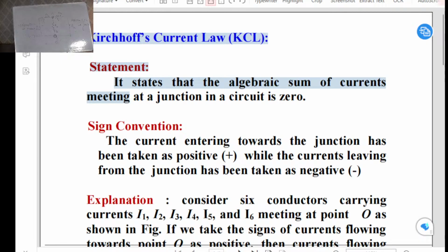If you draw any circuit diagram, this is confirmed. He is a scientist, he got the Nobel Prize also. He has proved it. Now, how to get 0? First, we should know the branch currents, small I1, small I2, small I3. Apply the mesh method or the nodal method, any one method, for the given circuit diagram. After getting the values of branch currents, substitute them, and you will definitely get 0. Then it is a valid circuit diagram.